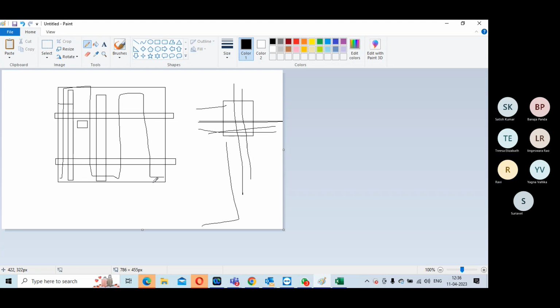Isolation cells are not for every pin, only whichever data is important, but every output pin needs isolation. Even power pins? Not power pins, no, power pins are not there. Means only data pins, data and signal pins. Means clock and signal pins. Yes, any output clocks and this one, that's where you need that.